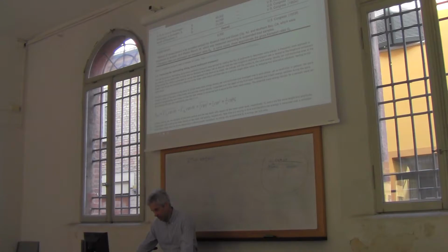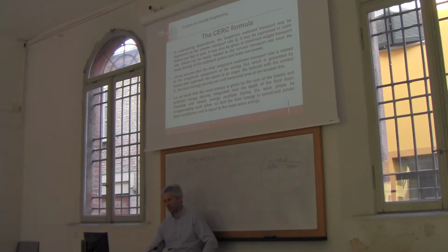Again, let's go back to the CERC formula. We can express the sediment transport again as volume over time or weight over time. It's easy to move from volume to weight, we will see it. There is a basic assumption in the CERC formula, which is written in the middle sentence.